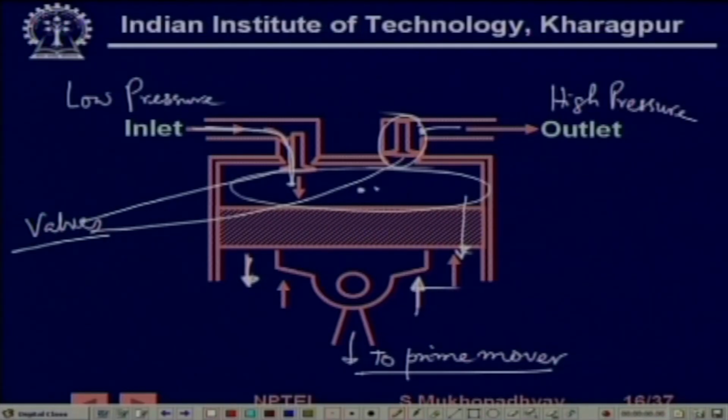After that, with this alternating motion, the cylinder will start going up. The moment it starts going up, it creates a high pressure here; it actually compresses the air. So, this valve is now pressed up, so it will be closed, while the other valve will also go up and open, so the air will flow out through this path.